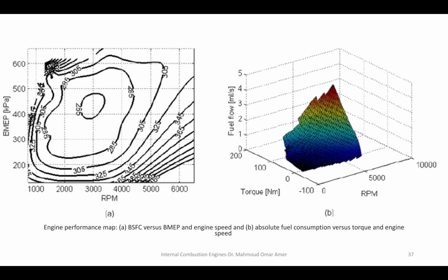These maps are 2D maps. They are a representation of the actual engine mapping, which is a 3D map. If you look at it from the top, and you take 6 sections, you get these rings. This one is inside the ECU of the engine. It's a 3D map. So the engine knows the RPM, and maybe the fuel flow, and knows the torque right away.